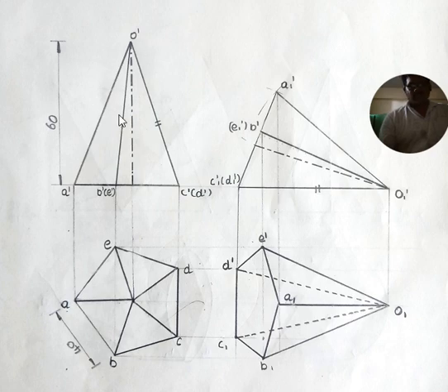So we have to tilt this first step front view in such a way that this OCD triangular face line comes on the XY line. In such a way, we have to tilt the first step front view. Then we have to reproduce the remaining parameters without changing its shape and size. So if it is tilted, we will get the second step front view. This is the second step front view after tilting the first step front view based on the given conditions.